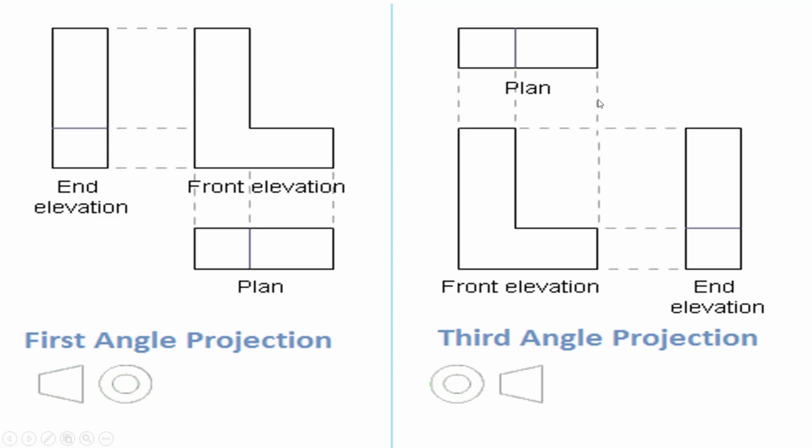If you want to see the top view, from the top you will see that the model's top view reflection will be on this ground plane, right? So here the front and here the top. If you move this plane clockwise and make it normal to the view, the front view will be first like this, and the top will be just beside it. It comes second.